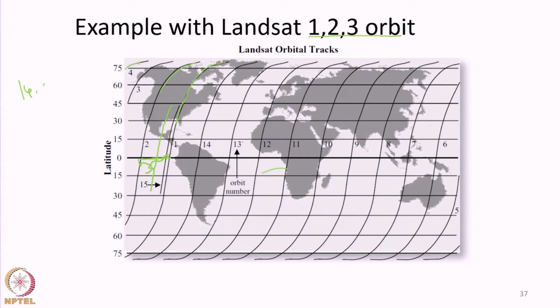For some other satellites it can be in a definite manner. So, all these things combined together will define the ground coverage of the satellite. Normally for the Landsat series of satellites, the distance between orbit 1 and day 1, orbit 2 and day 2 will be less than the swath width, so that we will get some sort of side lap between 2 orbits. Say swath width will be around 180 kilometers, orbital gap may be in the order of say 130, 150 kilometers. So, there will be a small side lap between 2 orbits every day. So, that common in-between portion will be imaged both on day 1 and on day 2. This is to enhance the ground coverage.